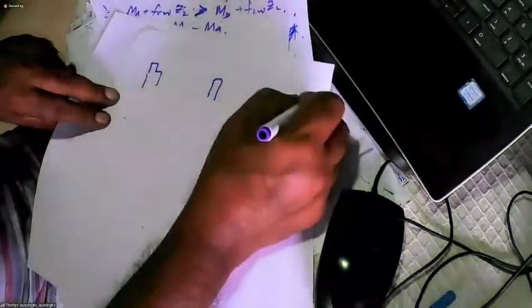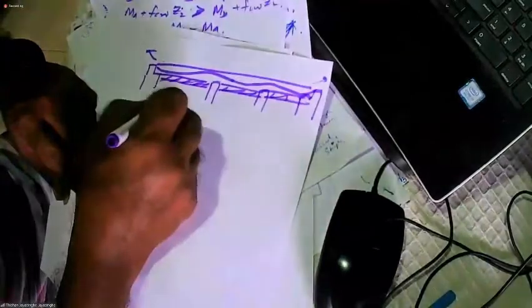So you have the abutment here, the piers here, piers here, piers here, abutment. So you have to have trusses here, here, here. Construct it continuous. Apply the tendons like that. Prestress it. Not easy.